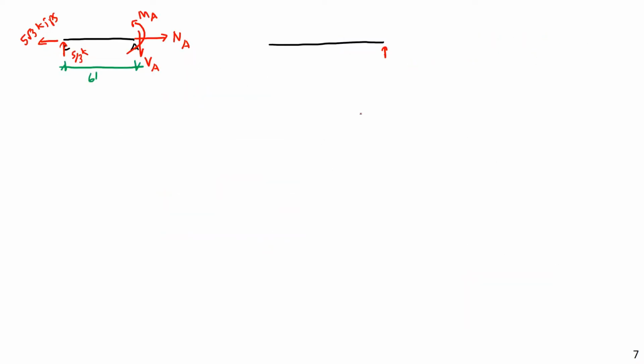Dy was equal to 10/3. I would have the 10 kip force at an angle of 30 degrees, and I could either draw that as one thing or as two. And then I would have the same internal forces, except they would be equal and opposite. So I'd have a normal force that would be stretching the member, but this time it would be going to the left, because it's also stretching. Another way to think of this is Newton's third law: these arrows do have to be equal and opposite. And then shear, if this one's going down, this one must be going up.